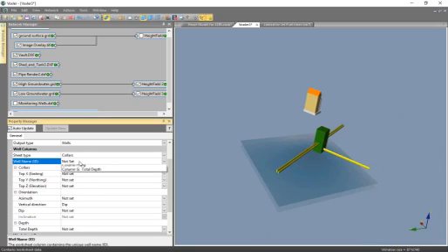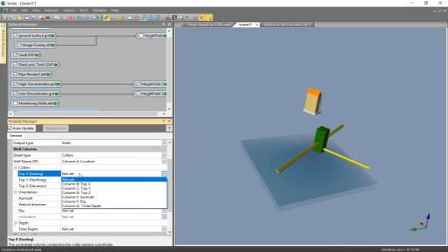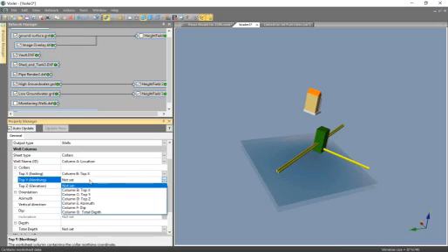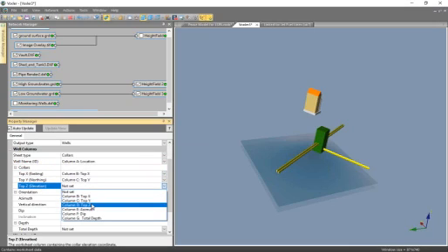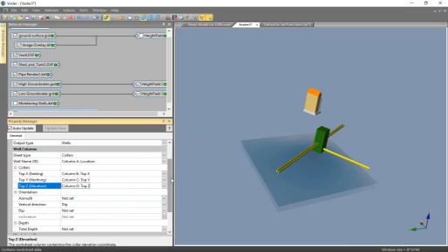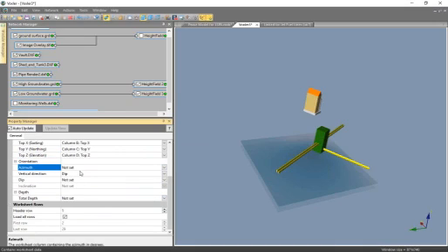And then for well name, I'm going to go ahead and select column A. And then I'm going to assign the rest of the appropriate columns. So for the easting, that'd be top X or column B. For the northing, that'd be top Y or column C. And for the elevation, we're going to use top Z. This data does include azimuth variables as well as dip, so I'm going to set those appropriate columns. And then finally, I'm going to set the total depth. Okay.